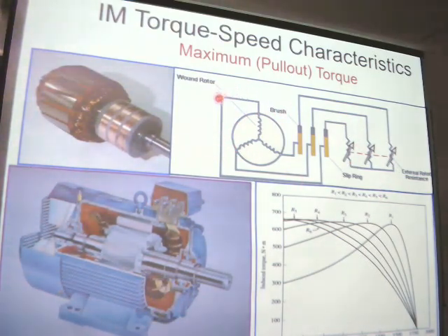So this is the rotor winding, and these are slip rings. The three slip rings, and this 3-brush is a Y connection, connected to the resistance. So this is the rotor winding, and it doesn't join the stator winding.